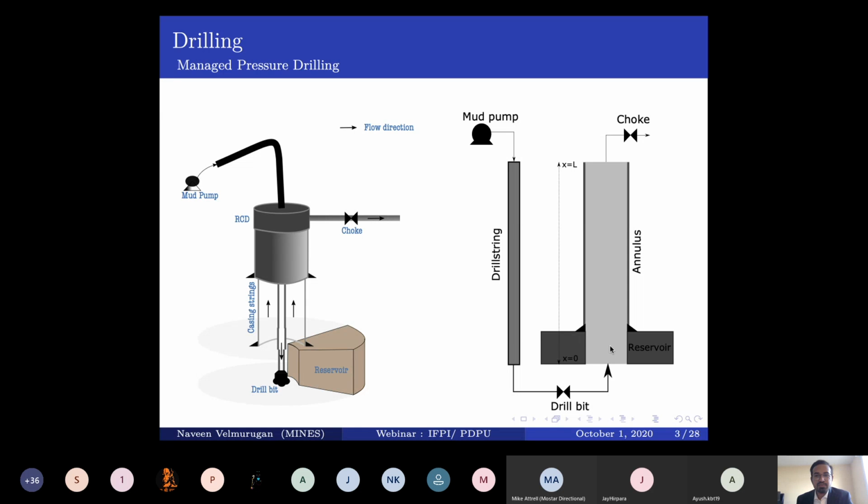So what we generally do is we simplify the schematic into the formulation that I've shown you on the right-hand side. You can see that the mud pump supplies the drilling fluid, and it travels through a particular pipe with a constant area given by a drill string. And then this fluid experiences a pressure drop at the drill bit, and that's what is entering into the analysis, right?